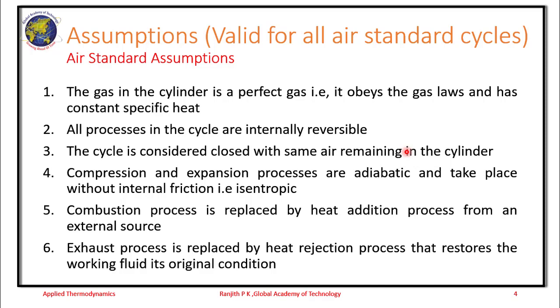This is very important. Whereas in the actual cycle, there is fresh air fuel mixture sucked into the cylinder, to analyze this thermodynamically, we have considered that it is a closed system and it is only air that is taken as the working fluid, hence the name air standard cycle. So this air circulates back in the system again. The compression and expansion processes are adiabatic and with zero internal friction, that is, these are isentropic in nature, and the combustion process is replaced by a heat addition process from an external source.